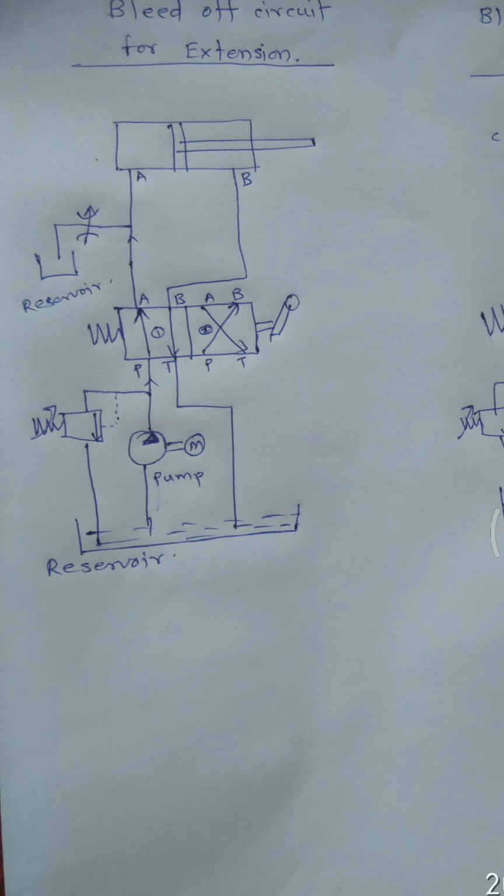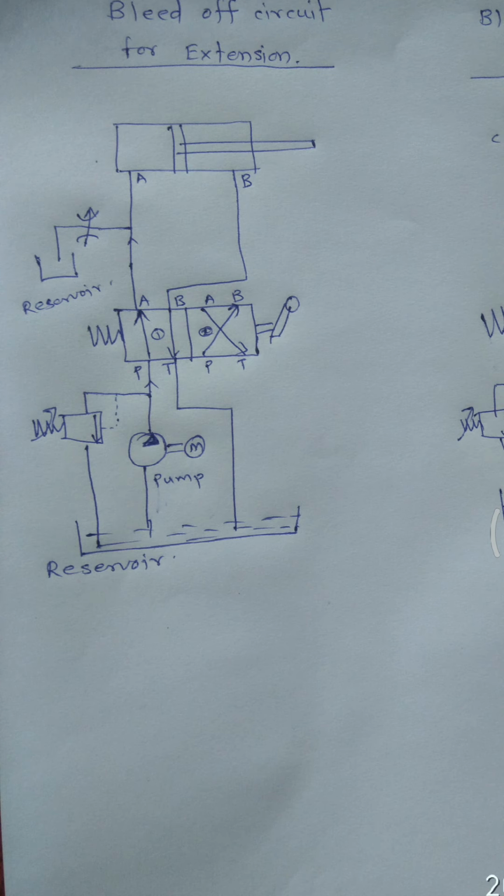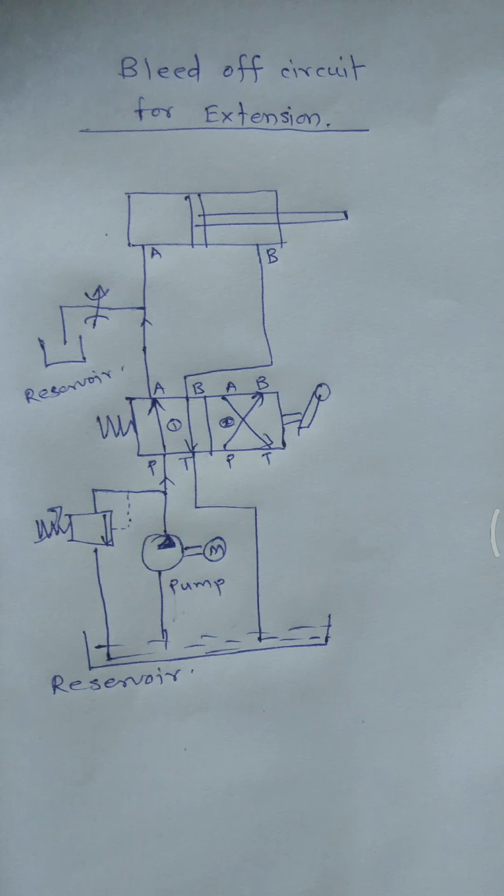So now I will zoom this diagram. This one is the bleed-off circuit for the extension. Like in each and every diagram or circuit, we need to begin from the reservoir. From the reservoir, focus on the central line. The pump is driven by the motor. The pump is pumping the fluid.